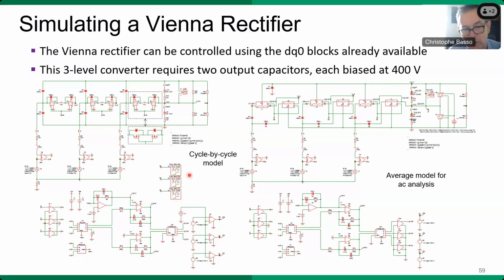And here, to extract the control to output transfer function, it was a bit of fun to determine it using 6 PWM switch models. So it's a heavy burden on the simulator's shoulders because it needs to find the right operating point. And here it's key to look at the DC value you obtain to really consider that your circuit is in regulation. But it works.